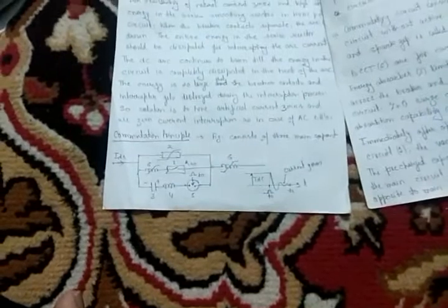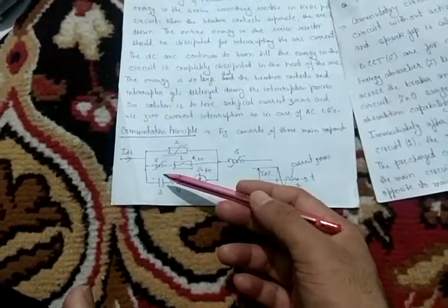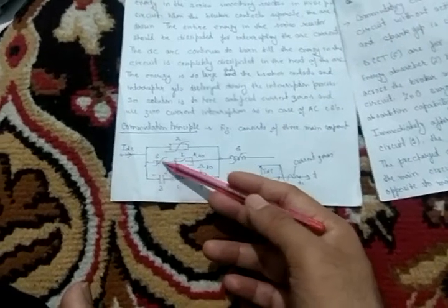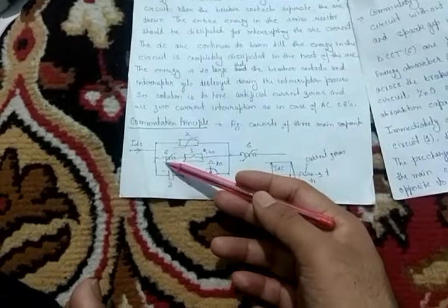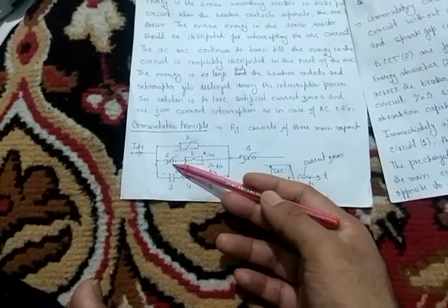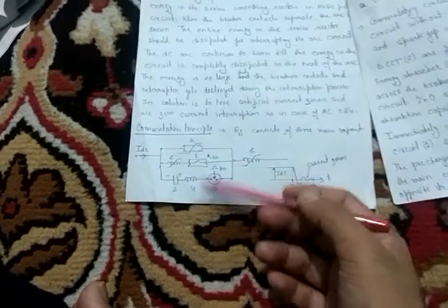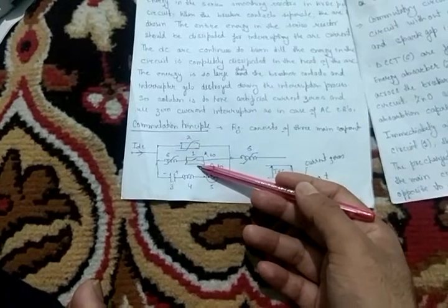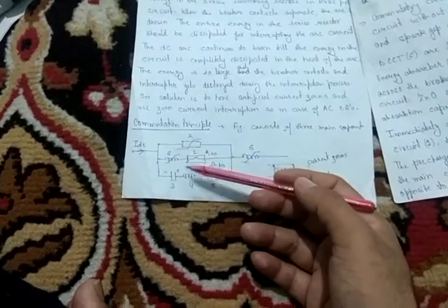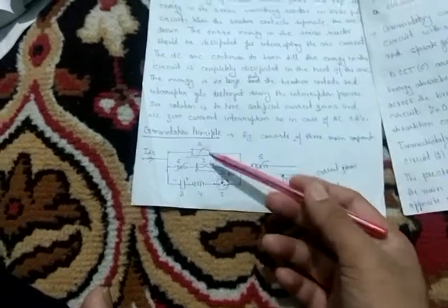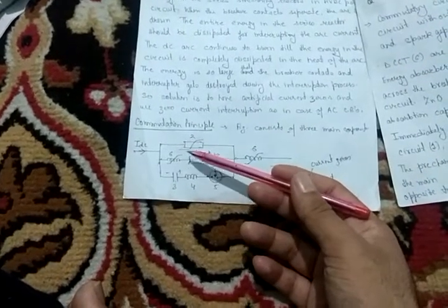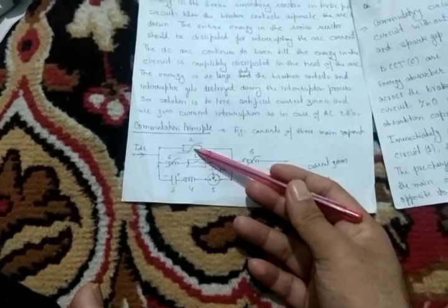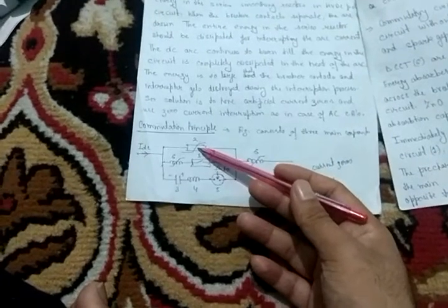Component 6, this inductor, represents the DC current transformer for measurement of current. It measures the current. Energy absorber 2 will limit the transient recovery voltage across the breaker, and it will absorb the energy in the main circuit. Zinc oxide surge absorbers have higher energy absorption capacity and precise protection level. That's why zinc oxide surge absorbers are used here. This 2 is the zinc oxide surge absorber.